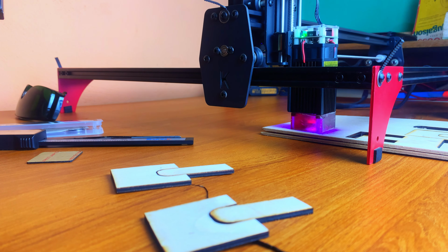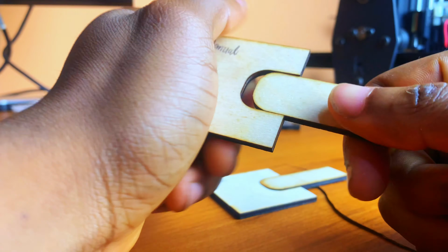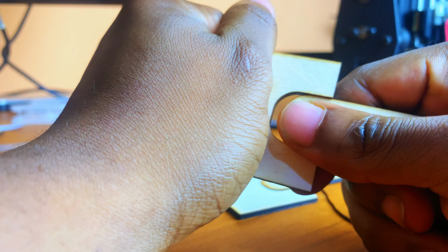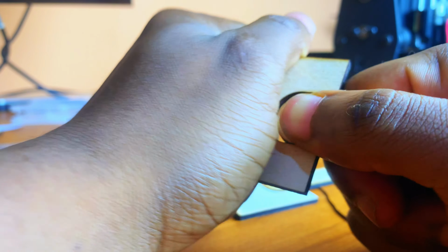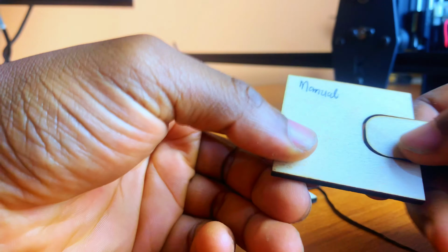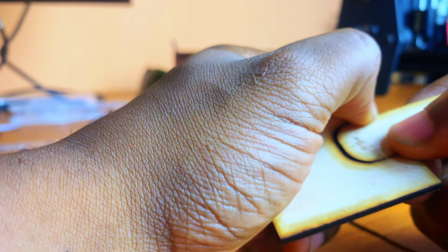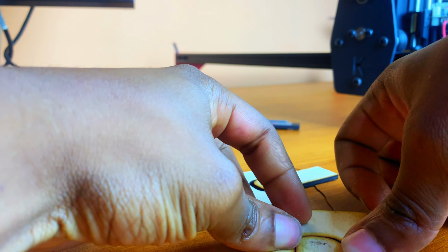It ran smoothly, and when it was time to test them, they fit so well, even better than the one made by inputting the kerf value in LightBurn. Pretty satisfying, to be honest. So as a recap, not accounting for kerf equals a waste of your time. Finding your laser's kerf and allowing LightBurn handle it for you is a good strategy. Also, manually tweaking your design using the offset feature is a good way to go to avoid the problems that come with not compensating for kerf.